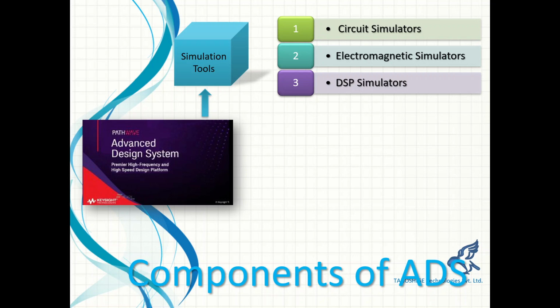So you can do your designs, layouts in ADS, and you will be able to take them with the click of a button to EMPro, so that you can do EM simulation. So method of moment is the classical simulator which has been there since the inception of ADS. Apart from that, there is FDTD and FEM simulator also, right?